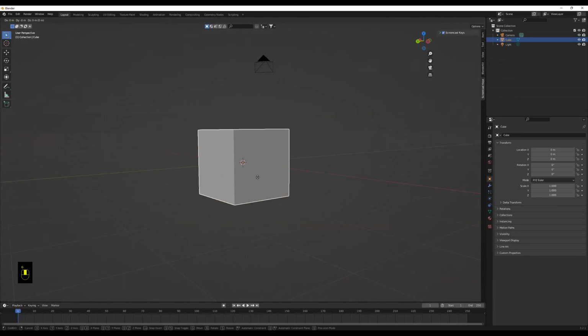I'm just going to call it a hat. Once you have that, you're going to extrude it again, but you're not going to move it up. You're just going to press E and then left click. That's basically extruded a layer right on top of our current layer. We're going to keep that layer selected and scale it outward. It has to be the width of the lantern. It's a bit thin of a line, so I don't know if everyone can see that, but it should reach all the way across from end to end.